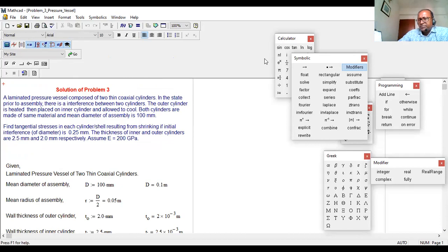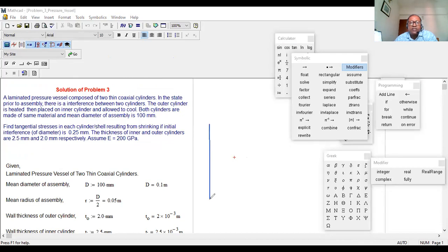Sir, can you tell again how did we use the value of yield strength in sigma T? Okay. Do you remember how the stress strain graph looks like? This is your strain. This is the stress of the material. So if you get like that, then yield strength, upper yield point, lower yield point, then going like that. This point means fracture strength. This is the ultimate strength.